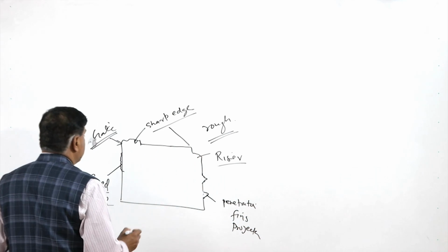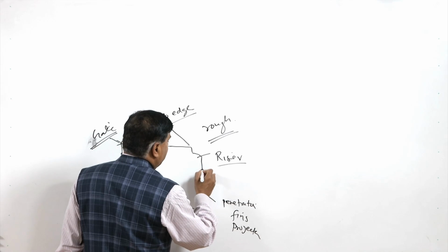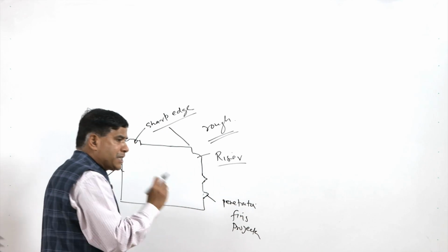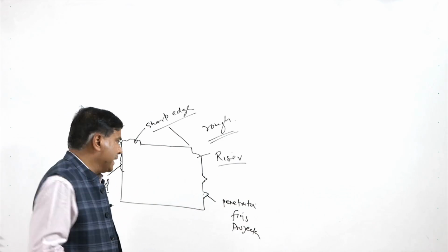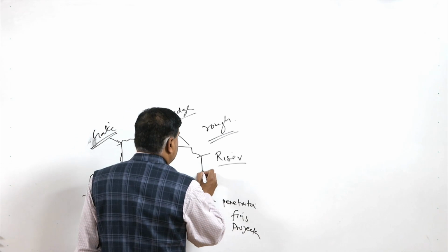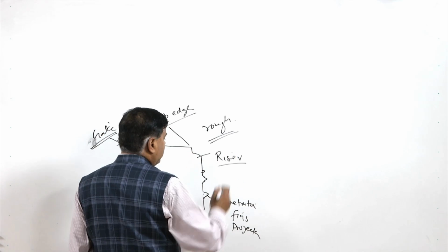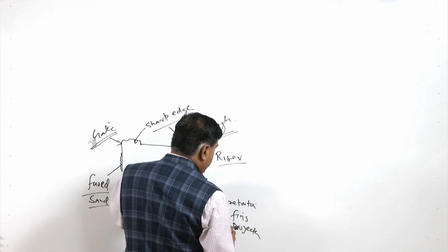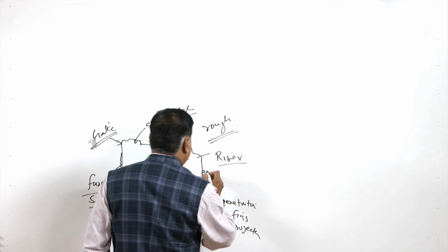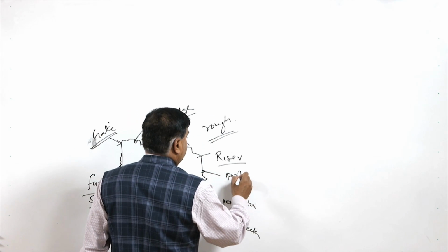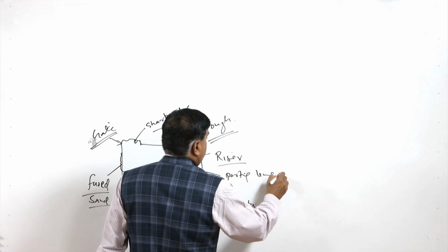So, these are basically penetrations or fins or projections. These projections may also be present at the parting lines in the form of additional metal deposited at the parting line. So, parting line metal may also be running along the length of the casting at the parting line. So, these need to be removed. So, parting line metals.